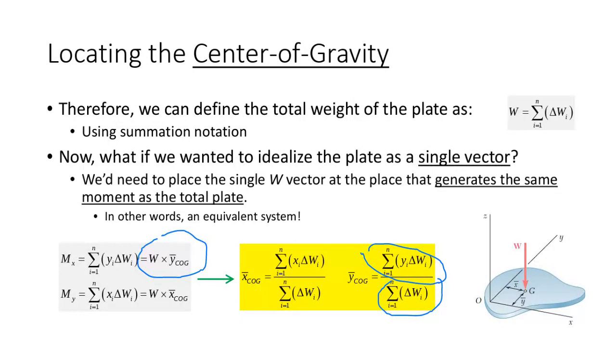Where is the center of gravity? It's the weighted average of all of your elements. You take each of your elements, multiply them by their distance from the y-axis, divide by the sum of the weights, and that's the location of the center of gravity measured from the y-axis. Same thing for the x-axis. That's simple. And I'm calling that the center of gravity because what you see here is in reference to weight. So is everybody with me on that concept? Again, if you can compute a weighted average, you can do this. It's really not that bad.